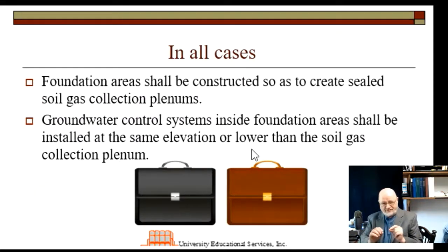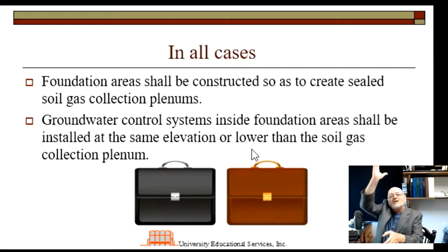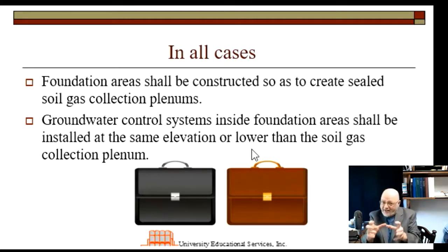In all cases, you shall construct, as it says here, the foundation areas so as to create, as I'm just reading, a sealed soil gas collection plenum. In this first bullet, what we're talking about is, remember, it's a soil gas coming up. What we're going to do is capture it before it has a chance to get into the building, and give it an opportunity to evacuate itself out into the atmosphere before it has a chance to get into the building. And so what's called the plenum here is simply the volume within which we're going to capture this radon and start its trip through its exhaust pipe.